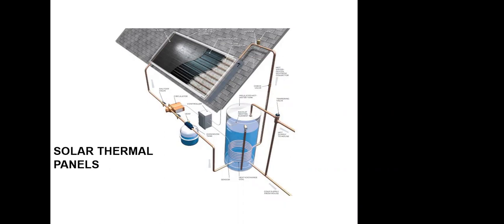So that tank, that's like the cylinder that we have over there. It's a hot water tank. So we can connect this to a boiler, we can connect this to solar panels or whatever. So we heat up water in this tank, and then we can use this tank for heating system or domestic hot water or whatever. But a hydronic system, it's always the same. Okay? Circulation pump, expansion tank, something that heats up water, and a tank. Yeah.